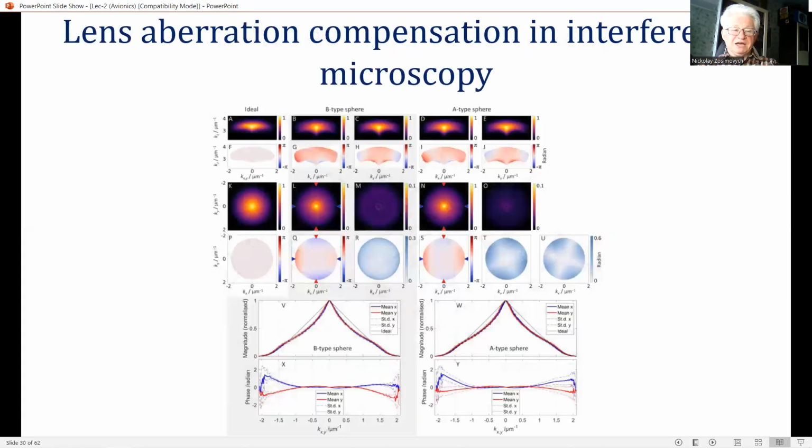The spherical reflecting surface of the combiner collimates the display imagery, but there are large optical aberration errors introduced which must be corrected. These aberration errors are due to the large off-axis angle between the pilot's line of sight and the optical axis of the combiner, which results from the HUD configuration.